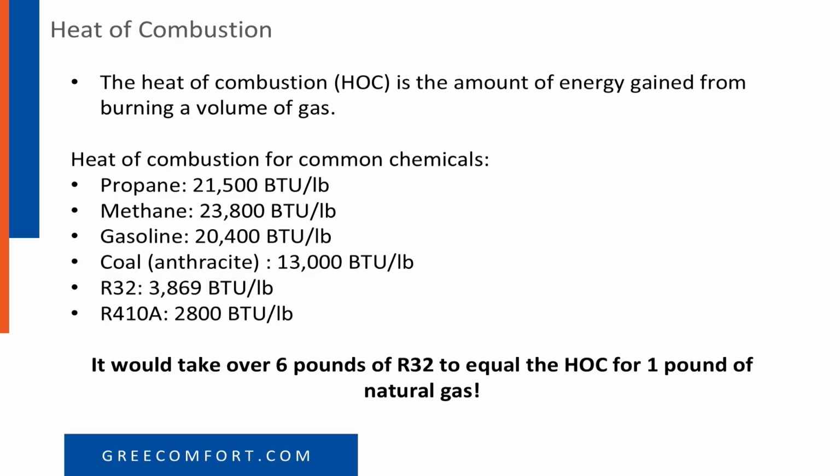Now let's look at R32, our malicious A2L refrigerant that everybody's scared of. If you burned a pound of R32, you're going to release 3,869 BTUs per pound. It would take burning over 6 pounds of R32 to equal the heat of combustion of 1 pound of propane.